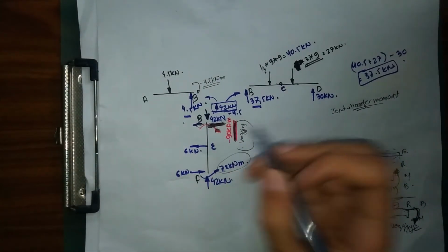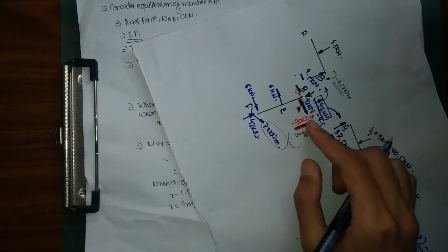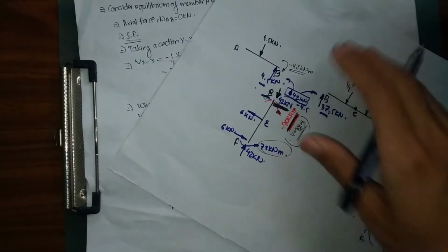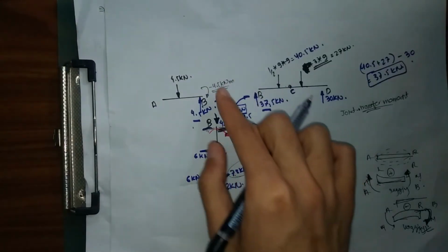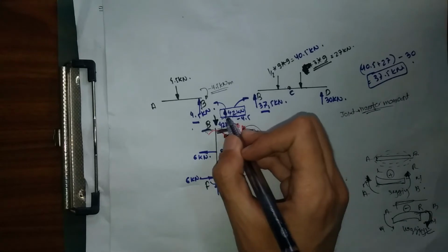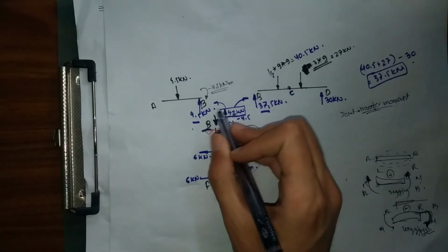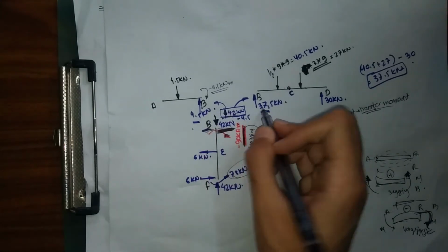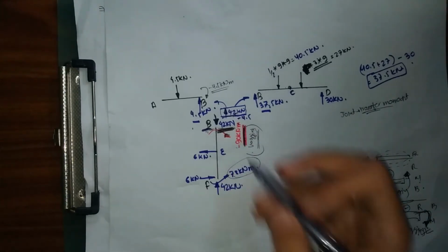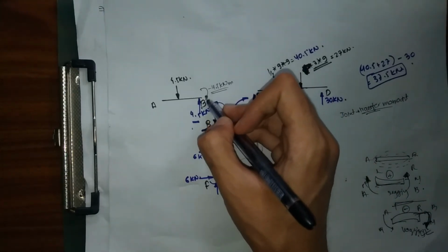it has got a little bit messier, but right now I have got minus 90 kilonewton meter hogging bending moment at joint B. So this hogging bending moment is going to get divided for member AB and member BD, like our 42 kilonewton got divided into 4.5 and 37.5. This hogging bending moment of minus 90 is also going to get divided. So I have already got 4.5 over here.